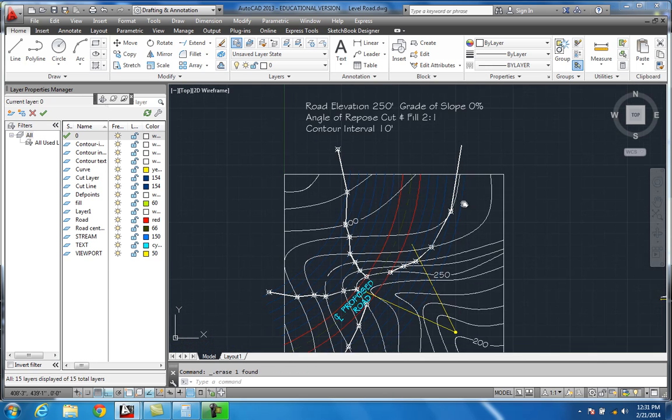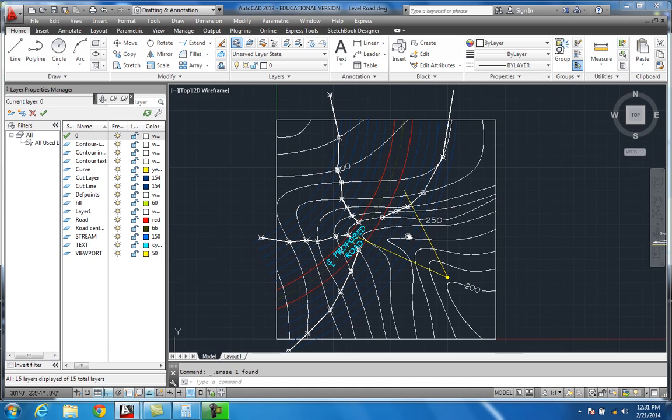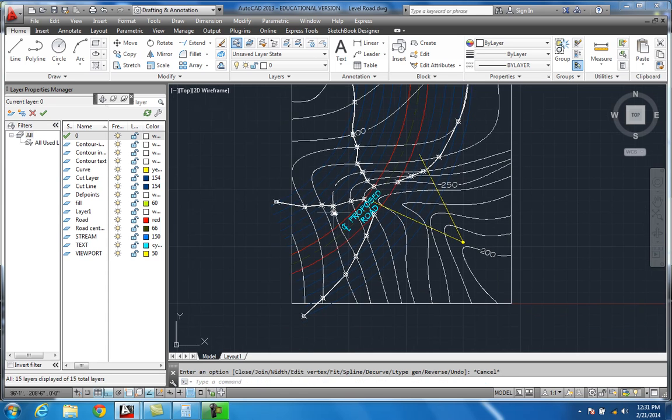And what I would do at this point is I'm going to polyline edit, p-edit, and you can come up here and grab these just to make it look a little better. And I want to do a fit, a P. It just smooths it out. It actually follows the points, but it makes a better looking smooth curve to it.